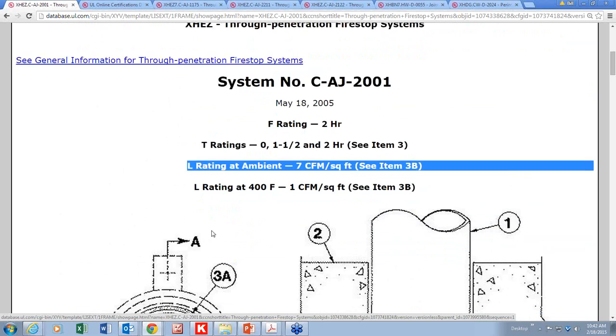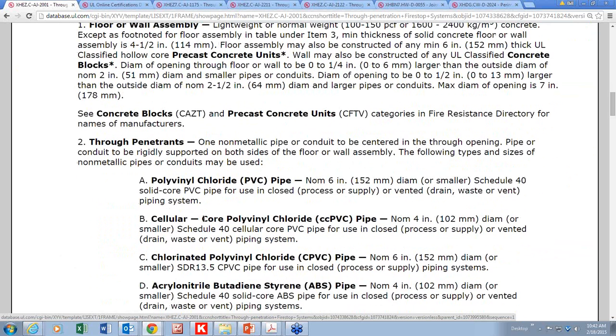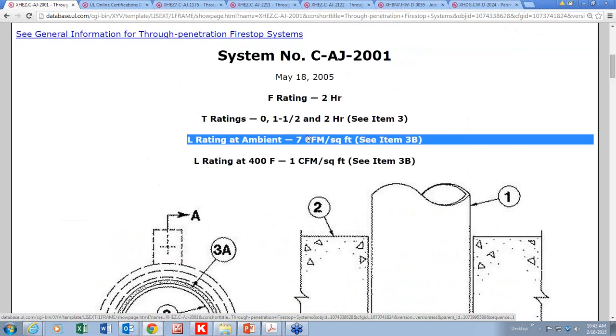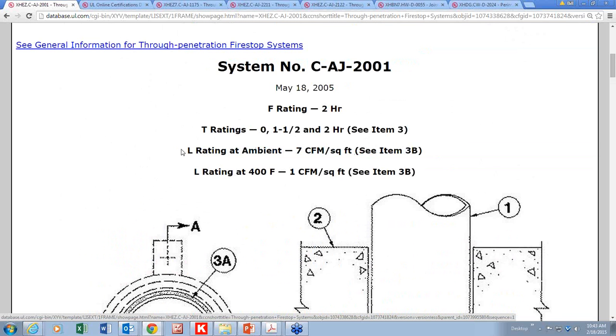This one's 2 hours. When people say that fire stopping is easy, and you'll see this all over the place, advertisements, contractors, everyone will say, oh yeah, just go get some firestop product and you're all set. The one thing that we would ask our building official friends and our specifier friends is, when you tell people to do firestopping, tell them to go get a firestop system. Just use that one word, system, because the system will result in someone providing this, the tested and listed system.